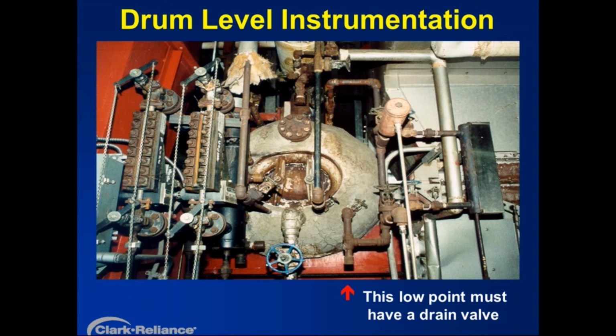Come to find out what happened where that red arrow is, at one point there was a longer pipe extended and a drain valve. One day the drain valve failed, they needed steam, and someone made a decision to just plug it and we'll replace the valve when we get a chance. And when we get a chance never happened, and resulted in both of those transmitters reading incorrectly when that sediment situation occurred. So it has since been remedied. I don't have an after photo of this one, but you understand what the concern was.